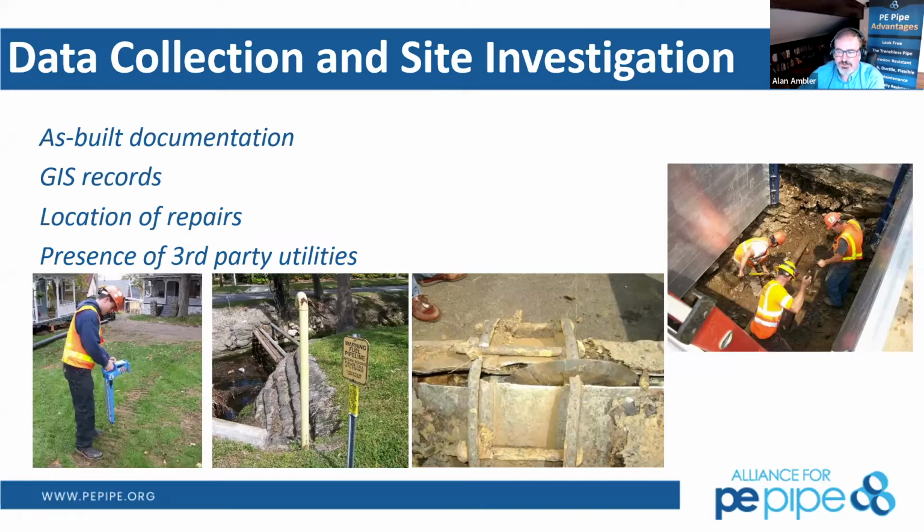Thank you. We've gotten lots of good questions coming in. One from Robert Allen talking about very large holes in the pipe, whether or not that would become a point repair prior to bursting. The bursting mechanism doesn't care about holes in the pipe itself. They'd simply burst through that. And then also, as long as you could fit the cable or the rods through the pipe, even if it's got root intrusion and other things of that nature, we will not need to come through and clean all of that out.